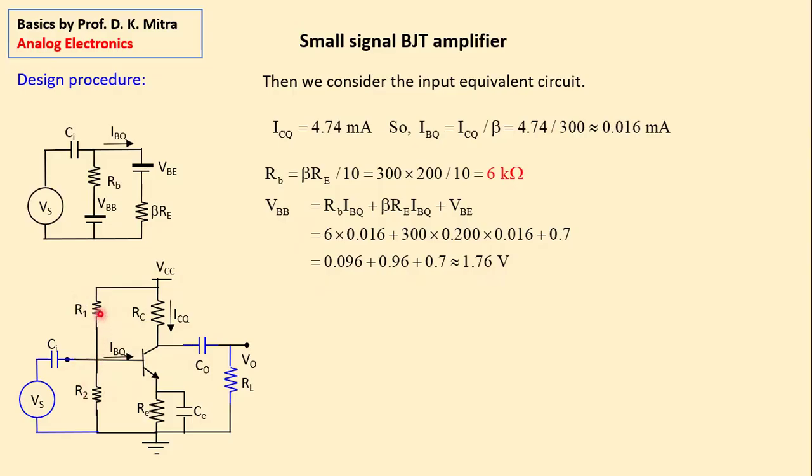Now, two equal resistances can be 10 kilo ohm and another 10 kilo, or can be 1 ohm and another 1 ohm. In both cases it will be 5 volt here. But how do you decide that? With much DC current flowing through this line, these resistors will get hot. Even it can create a problem with this power supply if it cannot supply that much current.